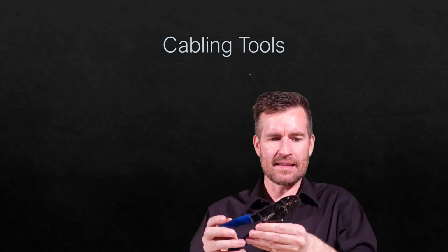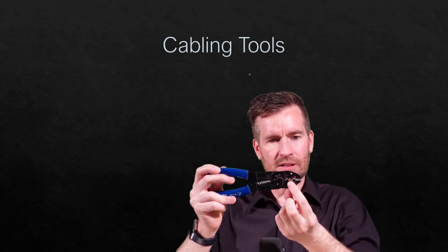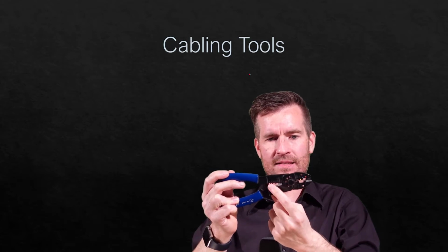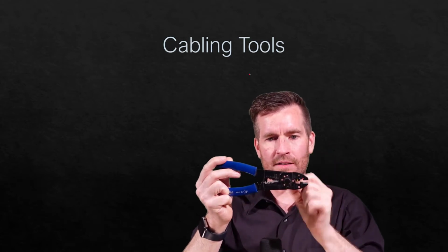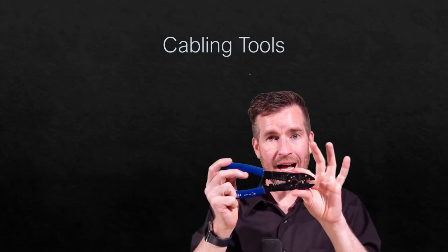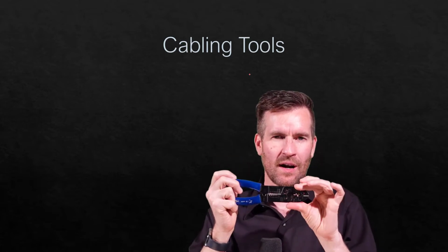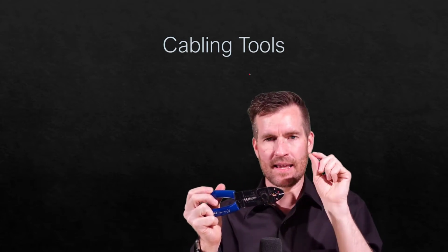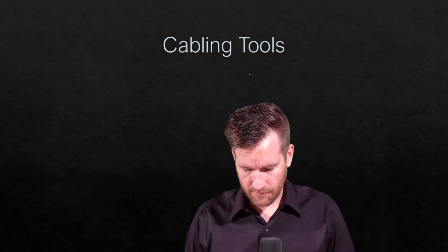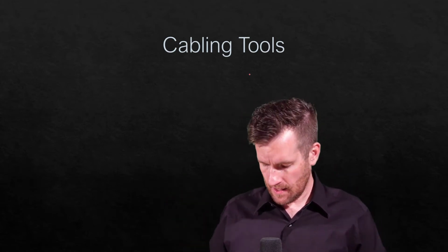And this is a wire cutter and stripper. Here, there's a wire cutter right here. The next little section on here will crimp certain connectors and certain ends. And then this section right here will actually strip the wire. It is for different gauges, and you can strip the insulation off the wire. So this is a tool that you could possibly see out there as well. I, once again, don't really see it. I probably have used it for some of the shielding and getting the shielding grounded, but I haven't really used this for cabling.